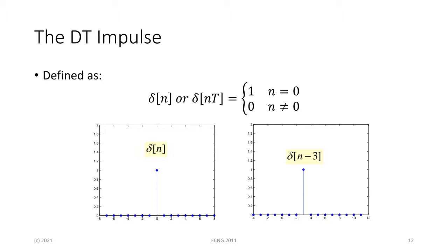Okay, so let's look a little bit now at the discrete time version of the impulse. This one is a physical thing that we create. It's something that has a value of 1 at sample 0, at t equal to 0, and 0 elsewhere. So for instance, in our computer systems, say plus 5 volts. If you have a plus 5 volt system, the 1 here will be a 5 volt signal just for that instant, and then it's off. Some computers now work with 3.3 volts, so whatever is logic 1, voltage-wise, would be whatever is the voltage supply for it.